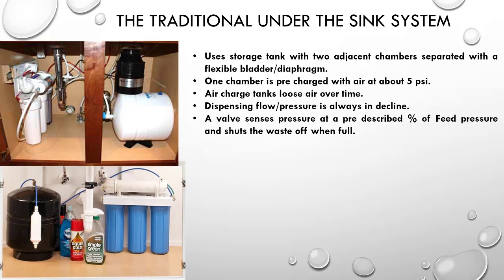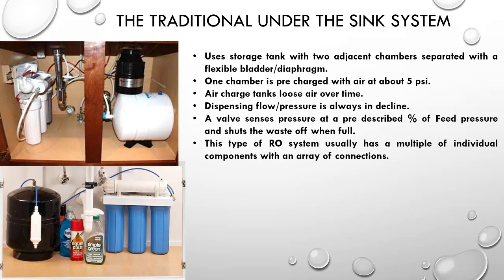A great feature with multiple cartridges is customization of cartridge arrangement to deal with the raw water quality. This allows you different size sediment cartridges. It can also allow you to utilize specialty carbon cartridges. And you can even now use cartridges that are becoming so much more popular, like alkalinity media cartridges for flavor or pH adjustment. This of course means that you've got excellent diversity with these designs.